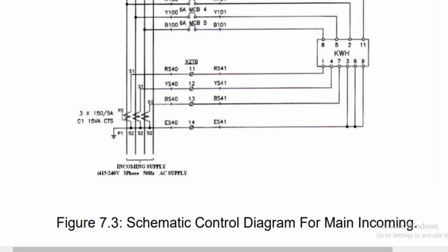Okay, we go to the current transformer. This is a step down transformer. As you can see, there are 3 times 150 to 5 ampere step down transformers. The transformer is used to measure the current of another circuit. It also produces an AC or alternating current in its secondary winding that is proportional to the current that it is measuring in its primary.